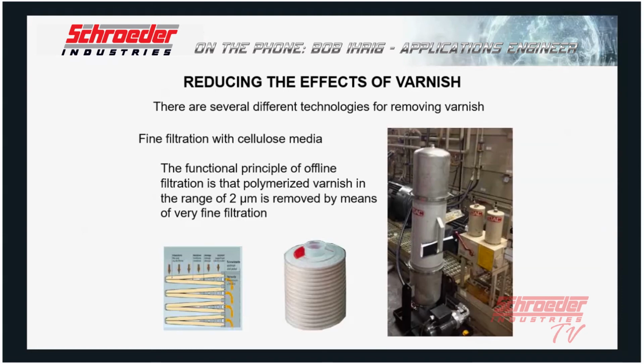The other way of doing this is mechanical filtration. So this kind of contradicts what I said earlier, that some varnish particles are so small that they can't be filtered, and that's still true. But if the fluid is cool enough where it agglomerates and is filterable, then using fine filtration, such as the OLF series, is a simple way of mitigating or filtering varnish from a system.